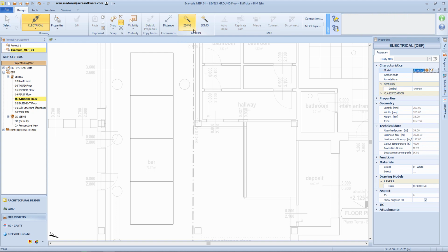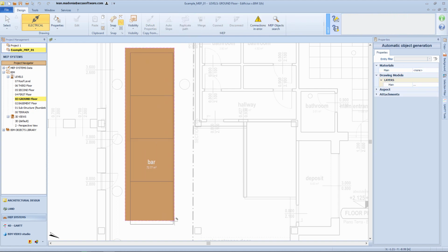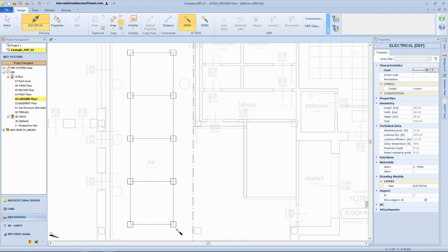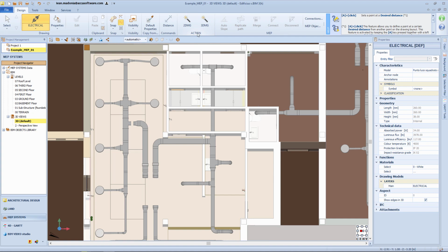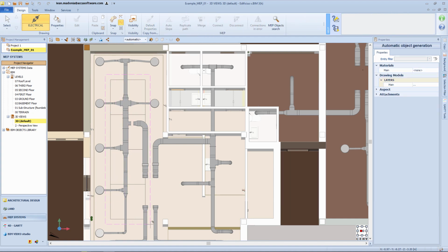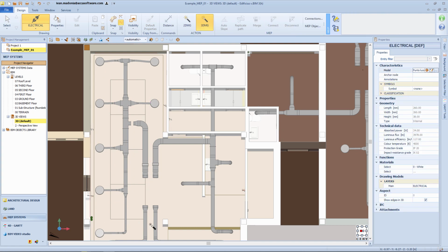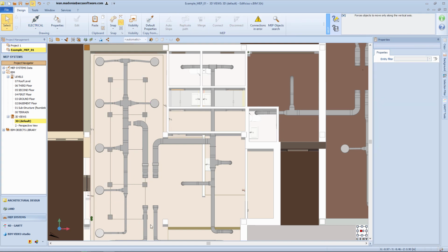Assuming you are proceeding in 2D, you choose the 2D option and with the magic wand thus activated you select the grid already arranged on the drawing. As a result, you will get the insertion of a light point object in each of the intersection points of the grid lines. In the same way, in the 3D environment, the magic wand is activated by selecting the appropriate button and, with the light point entity active, the grid is highlighted to automatically obtain the arrangement of the objects at the same delta set for the grid.